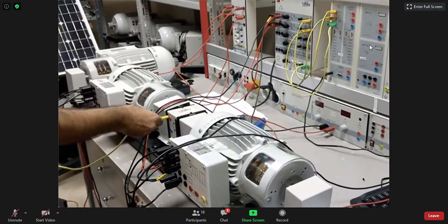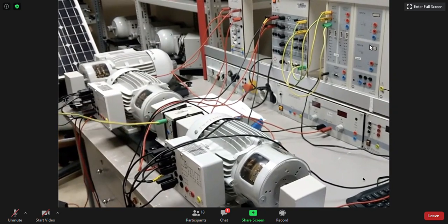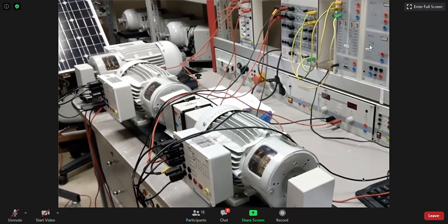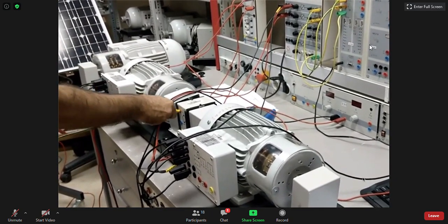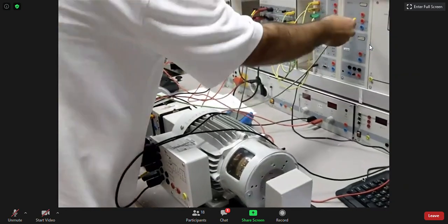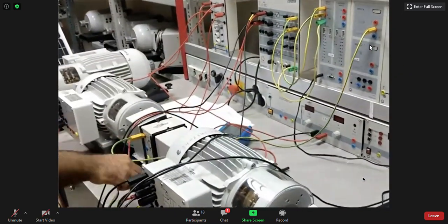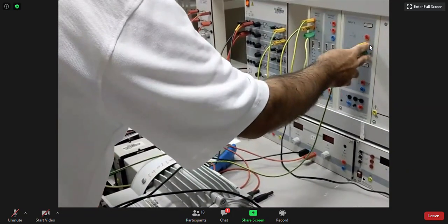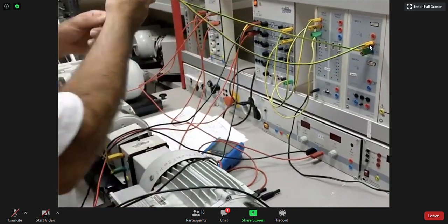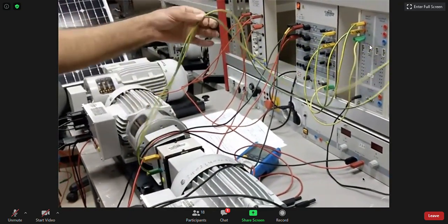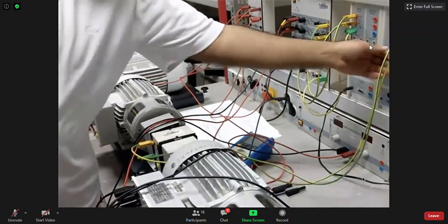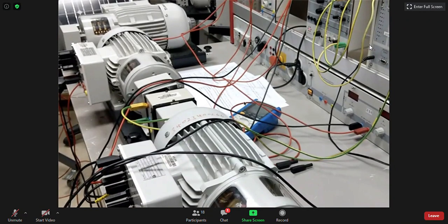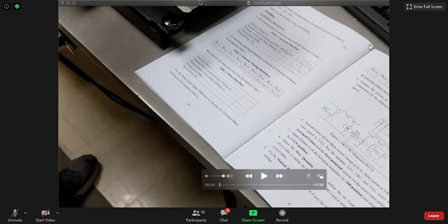So the tachometer, as we said, will have a very small voltage. We don't need to use the isolation amplifier with the tachometer. We can just connect it directly to the CASSY sensor. So this is the tachometer. This is UA2. And again, the neutral is connected to the neutral here. Again, we said you need two terminals to measure a voltage. So this signal will be a voltage signal representing the speed. Is it clear? Okay, gentlemen, the circuit is connected.